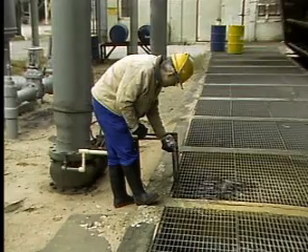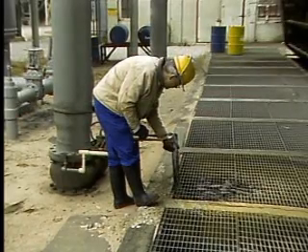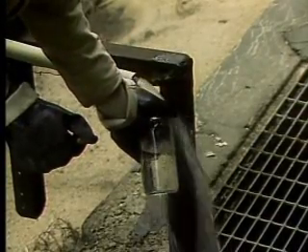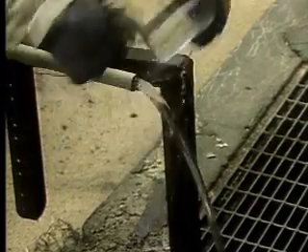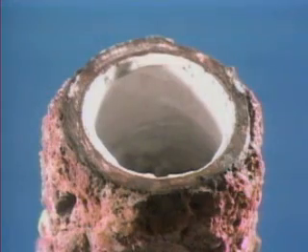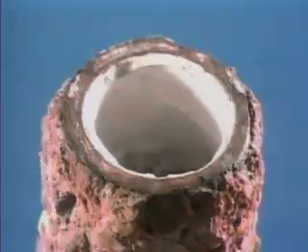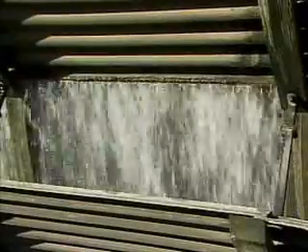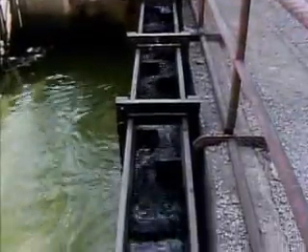Chemicals such as calcium or magnesium are often found as dissolved solids in cooling water. These impurities can become concentrated, come out of solution, and cause scale buildup. Scale buildup on the inside of a heat exchanger can reduce heat transfer and restrict water flow. Now, there are several ways that dissolved solids can concentrate to form scale. For example, when water evaporates in a cooling tower, the solids are left behind, and the concentration of solids becomes higher in the remaining water. Also, untreated makeup water may have high concentrations of dissolved solids.